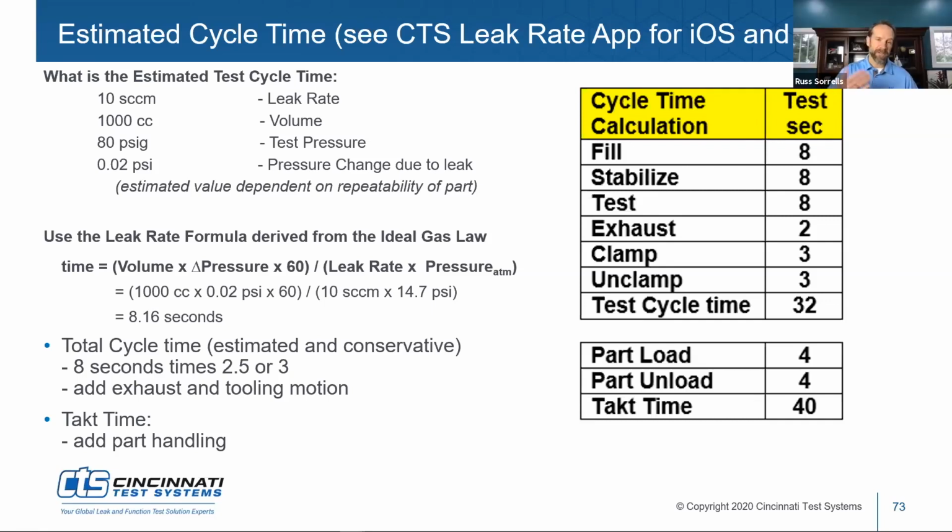Absolutely. Thank you for sharing. And sorry to put you on the spot there. No, that's no problem. That's a common thing because the customers are like, should I test at 50 or 100 or 200 psi? And the reality is, well, we don't really care. What matters is what is the leak rate that you're trying to eliminate at the pressure that your part is going to operate at, or the max pressure that your part will see in operation. Exactly.